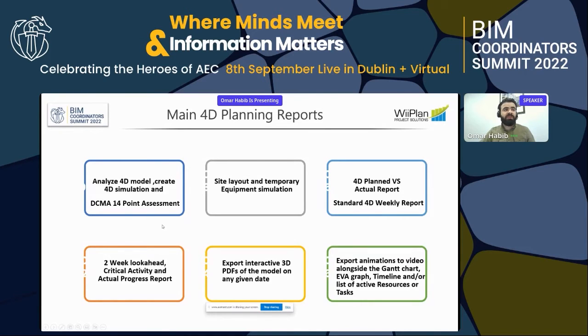Every day they do 4D analysis and create 4D simulations, the DCMA 40-point assessment, which is the analysis of the time schedule itself, site layout and temporary equipment simulation, and this actual report, which reviews and explains the actual situation versus the planned situation. Sometimes we integrate reality capture with the 4D, so we get the realistic actual versus the planned from the 4D model. One other very important point is the two-week look-ahead, and you can monitor your critical activities and actual reports, and you can even export your information to a PDF, a live PDF.